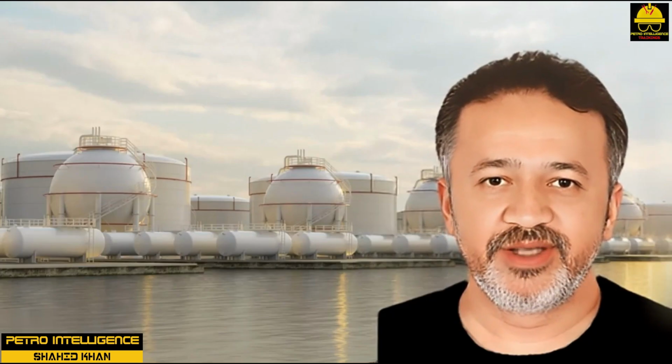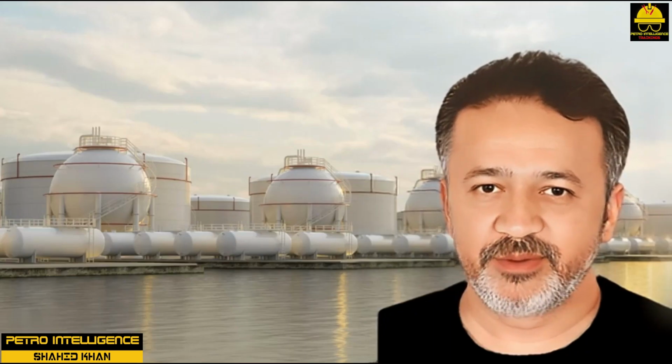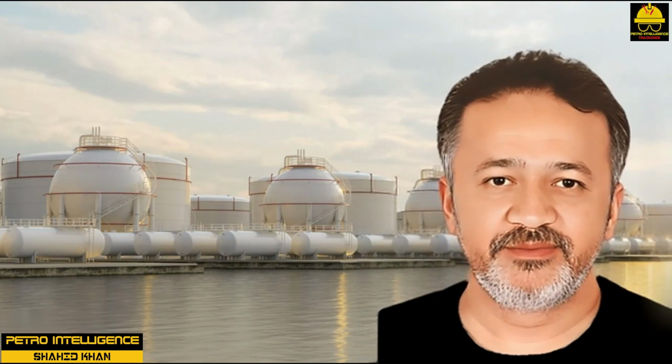Cast iron piping. Cast iron pipe and fittings are used to convey non-flammable fluids in some areas. The sizes and thicknesses of cast iron pipe are similar to those of steel pipe. Because iron becomes brittle when it is exposed to fire and then sprayed with water, there is a good possibility that the cast iron would break under those conditions. For this reason, cast iron piping is not used in hazardous areas, nor is it used to handle flammable materials in any area.